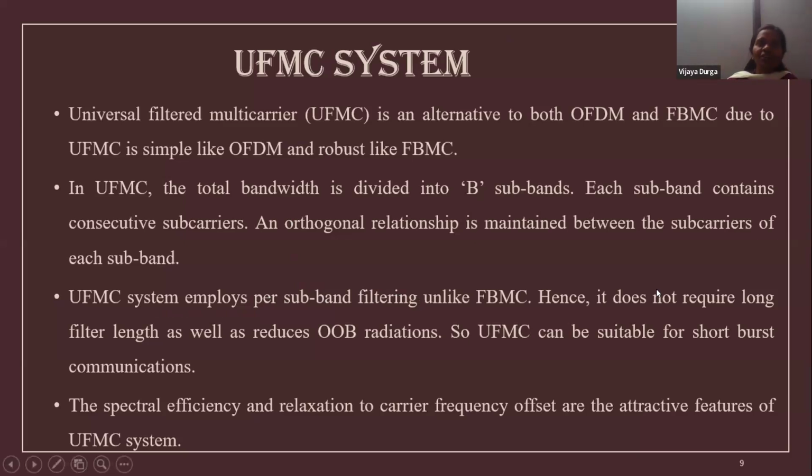Hence, it does not require a long filter length. As we are using filters, especially the Chebyshev filter, it can effectively eliminate out-of-band radiations. So UFMC is suitable for short burst communications and IoT. That is the beauty of it, so it can integrate with IoT.